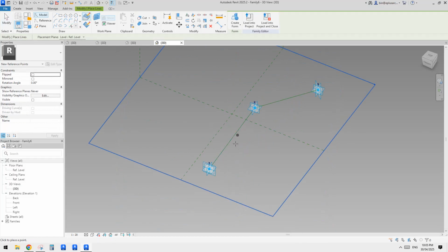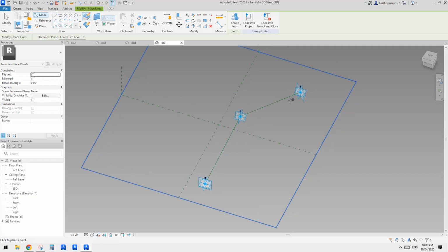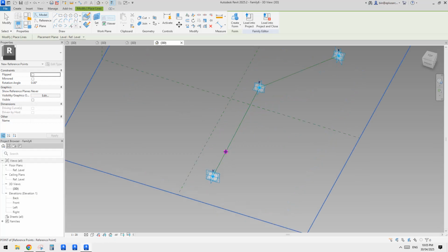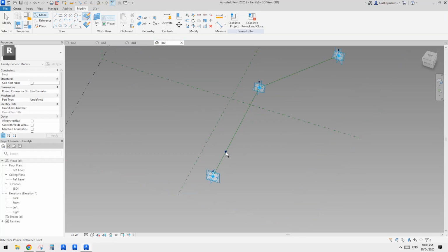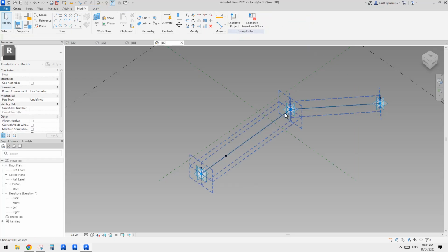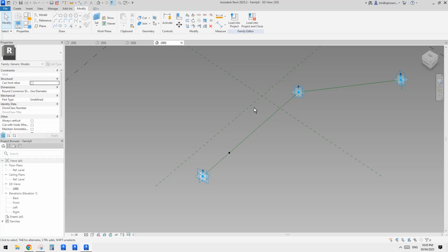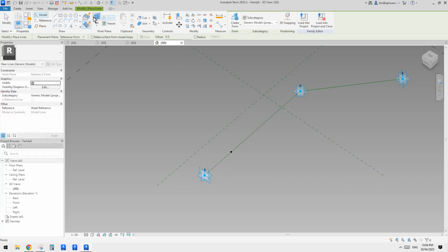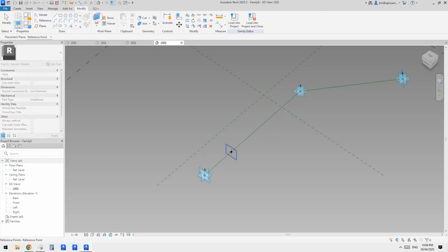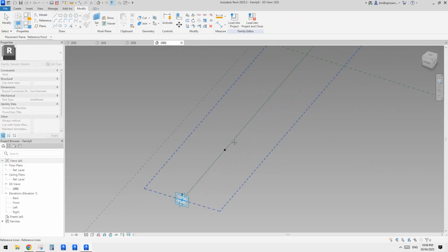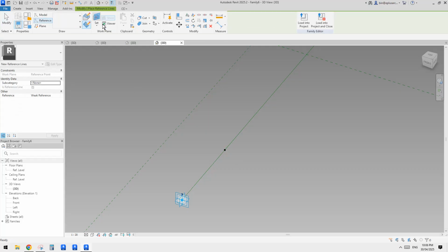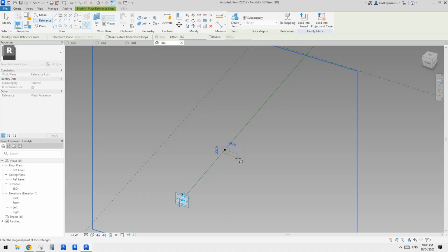So let's do the vertical. Let's imagine this is a vertical part. This is the diagonal, the slant part. So place one point, you draw on face onto this first. Okay, and let me think. We will place two profiles, one at the bottom, one at the top, almost the top. So let's use a rectangular shape, draw on work plane, set work plane, and let's just do a rectangular shape. So, reference rectangle, draw work plane, set work plane, pick the work plane, draw the profile.